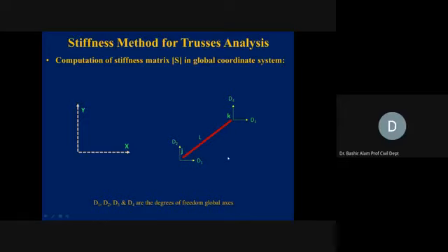So this is how, by the time we start pushing it to the right, it means we are inducing compressive forces in this member 7. We'll discuss this at joint K, but for now you should understand how we assume the direction of the force induced when we start giving it displacement in the right direction. It will be compressive. Compression means towards the joint, and from here also towards the joint.